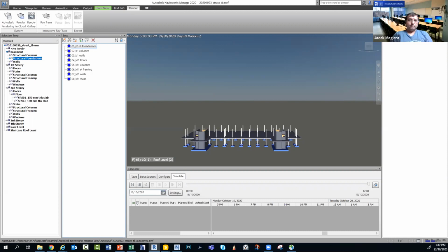But of course, if you go with Navisworks, there are certain things that Solibri can do that Navisworks can't. Say, for example, you want to design your own rule set. It's not possible in Navisworks. There are some predetermined fixed things that you can do, but it's still very rigid. But if you want to design your own rule set to check your model, then of course I will recommend SMC.